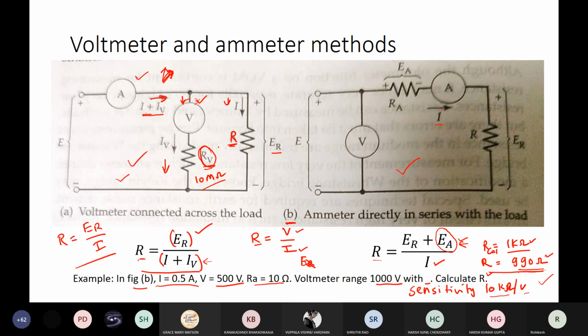No. What it means is, I will give you an example. Let's say the ammeter indicated 2 amperes when the voltmeter was connected. And when you disconnect the voltmeter, let's say it indicated 1.5 ampere. So what does it mean? That the voltmeter was consuming significant current, isn't it?